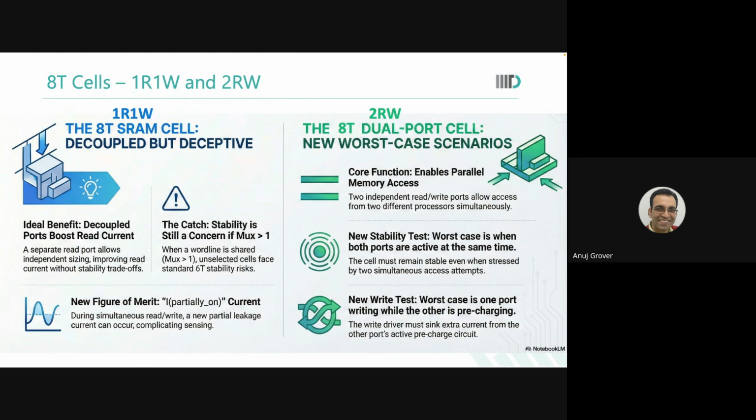But before this precharge could turn off, something like that happened. Now, since this precharge is off, it already started to discharge. And there was a duration when both precharges were off. Even though I had taken care of everything in the static manner, the relative spacing between my clock 1 and clock 2 led to extra discharge on the other port, and I ended up reading wrong.